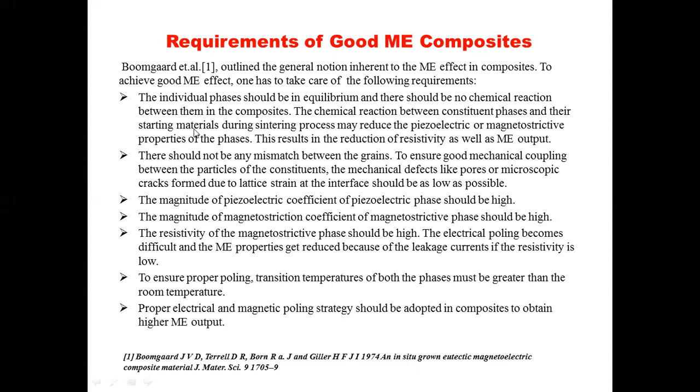And the next point is that the magnitude of the piezoelectric coefficient of a piezoelectric phase should be high. So we have to use one piezoelectric material, and the magnitude of the piezoelectric coefficient of that piezoelectric phase should be as high as possible, so that at minimum applied electric field, we are getting a more piezoelectric effect. So that is a very, very important point.